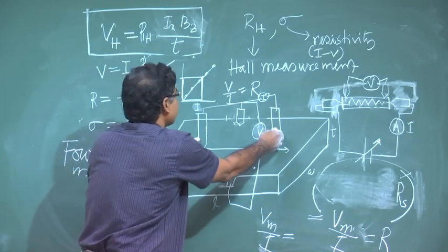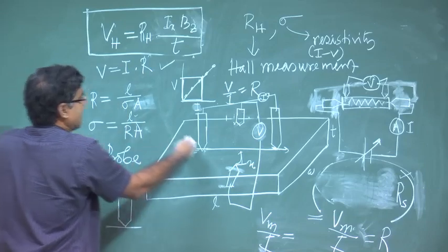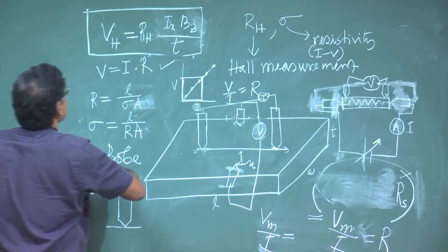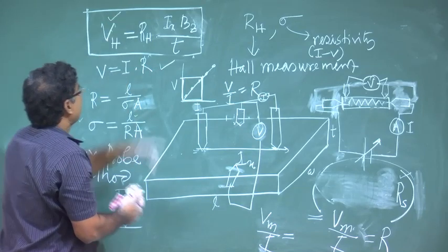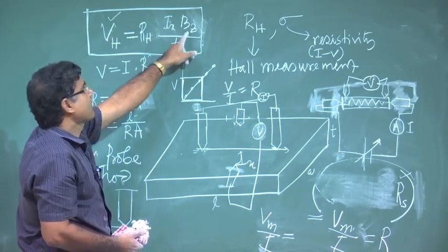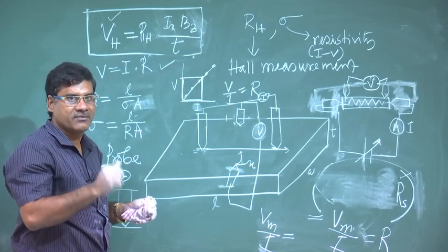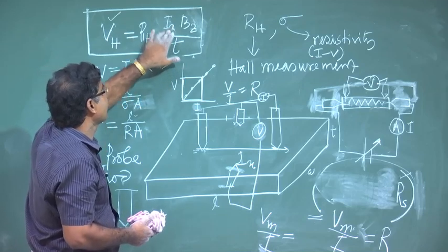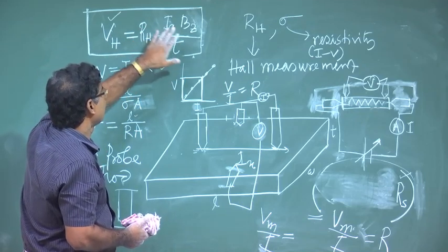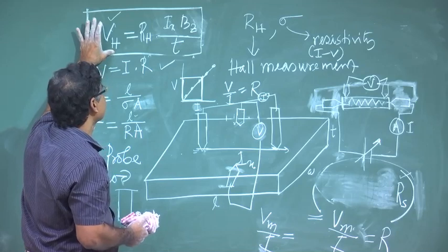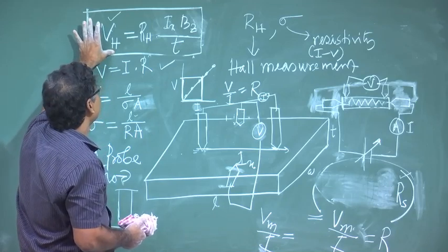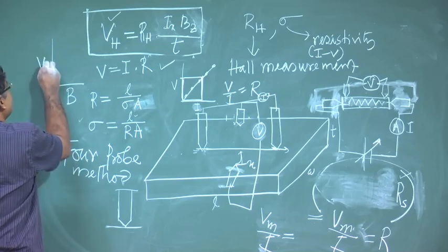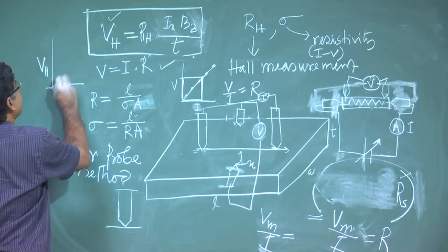Okay. Now, you are setting current Ix along the x direction, and you are measuring the Hall voltage, applying different magnetic fields, just vary the magnetic field, and get this Ix, get this VH, okay, and then if you draw a curve of VH, you will get, I think, a linear type of curve.